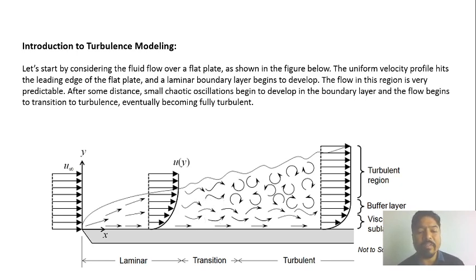The viscous forces are now reducing, hence turbulence starts to form. So in this transition region, the fluid flow becomes turbulent. After that, we have another region, the last region towards the trailing edge of the plate. You can see that we have too many variations in the fluid particles when they are flowing in that region. So we have turbulent boundary conditions over there.